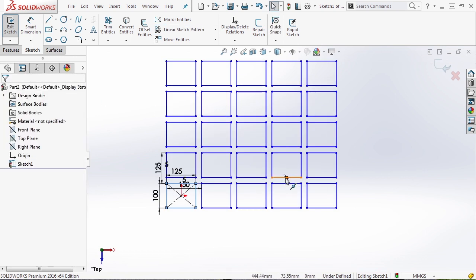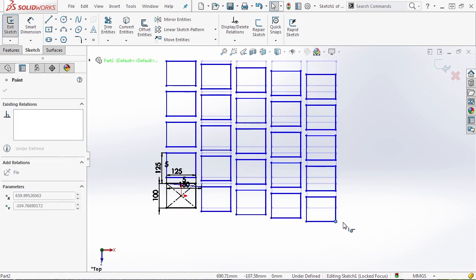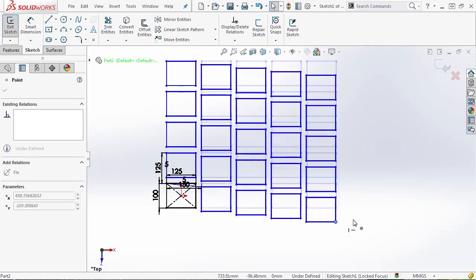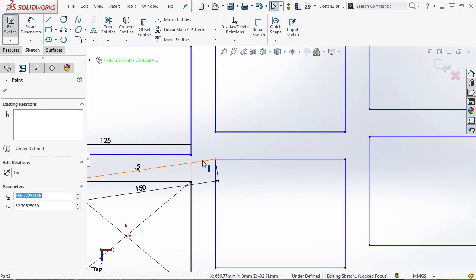One thing you'll notice is that all of the entities are blue. Now, this happens quite a bit, and one thing you'll notice is that they're free to sort of float around. Now, in order to fix this, you notice that there is a construction line here, and it's giving us the spacing, 150 millimeters, the instance count, the number 5, and then this line right here.